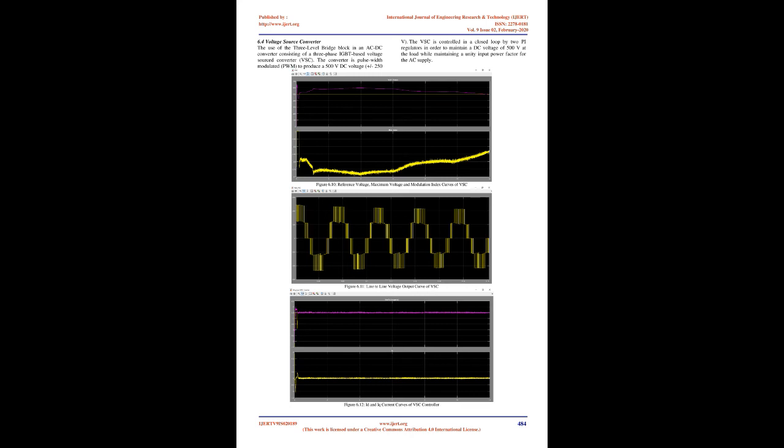P-V and I-V plots for 3 different conditions are defined for the PV array, i.e. 1. P-V and I-V curves for the PV array at constant solar radiation of 1000 W/m². 2. P-V and I-V curves for the PV array at constant ambient temperature of 25 deg.C. 3. P-V and I-V curves for the PV module at constant ambient temperature of 25 deg.C. A few 1D lookup tables are used in the modeling of the PV array. The data used is as follows in the tables below. Figure 6.4, P-V and I-V curves for PV module at 25°C.